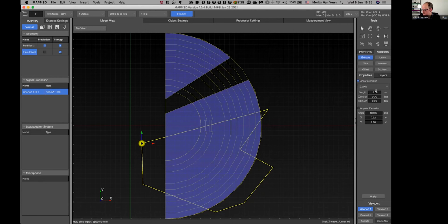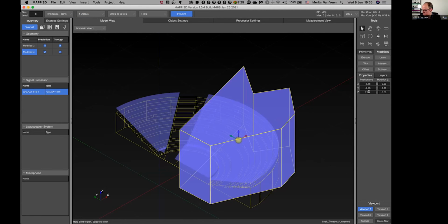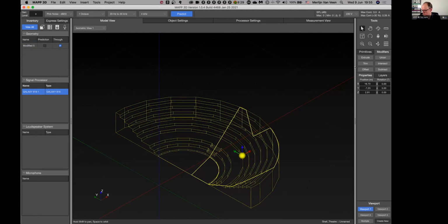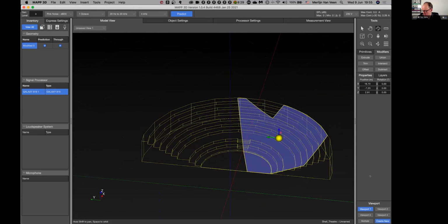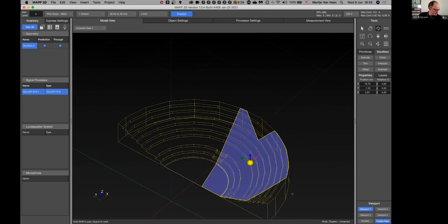So it's a great tool, and you draw the shape that you want. It could be any shape, and using the snapping tool that Merlijn showed is also great to lock to the shape of whatever geometry you're working in. Then you extrude that shape that you draw and bring it down to where it's covering the whole entire surface that you're trying to cut out, and then click intersect, or you can click subtract, and there you go. So this is really the way to come up with complex shapes very, very fast. So that is your first sample of how to add geometry.